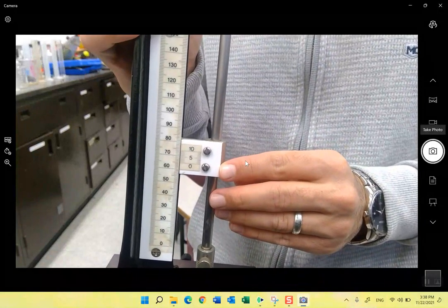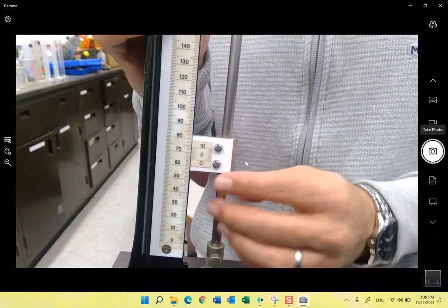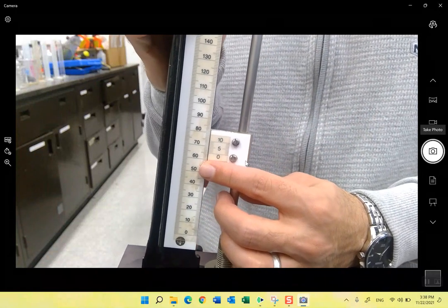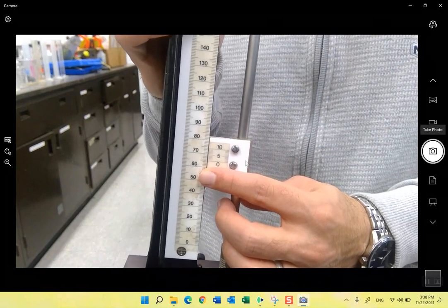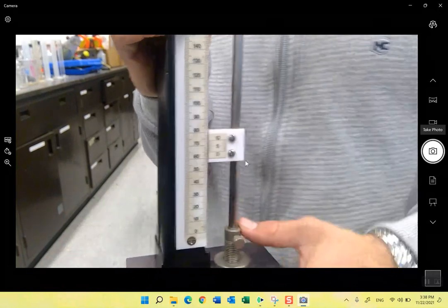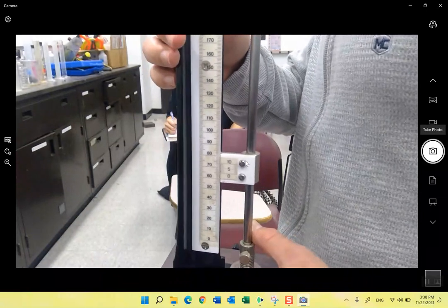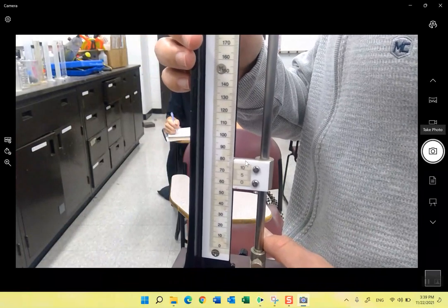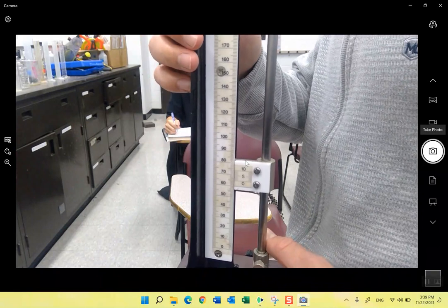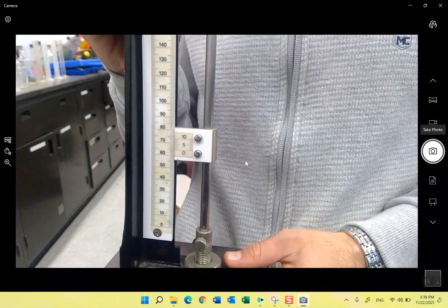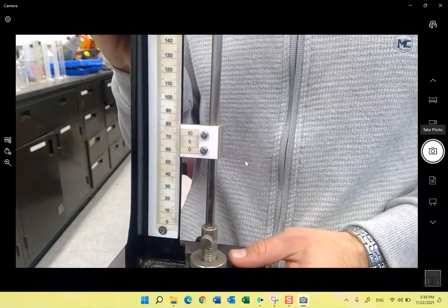In this case, the zero is at 60 something, right? Should be 64 or 65, right? So using a regular ruler, you won't be able to get the actual first digit, let's say. You will just guess, okay, it's between 64 and 65, so I will take it as 64.5.